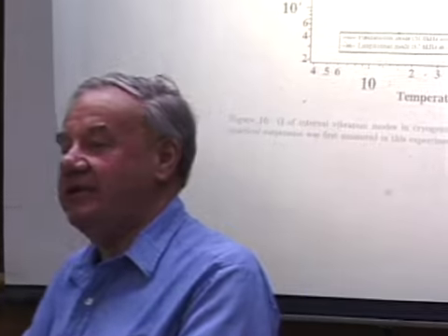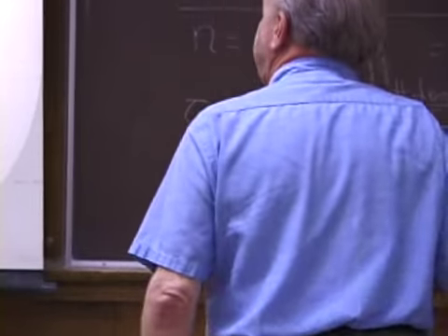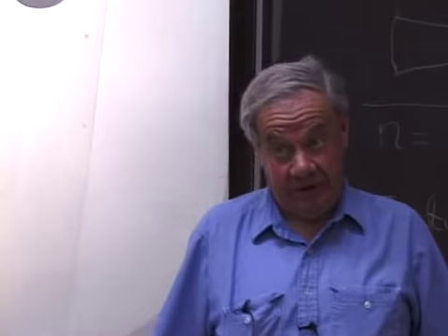So you don't gain as much as you might think. In fact, a much more significant effect than the plain reduction of the temperature, and thus of the thermal noise, is that the Q of the materials you're going to use gets a lot better at low temperature. That turns out to be a bigger factor than the temperature itself falling.